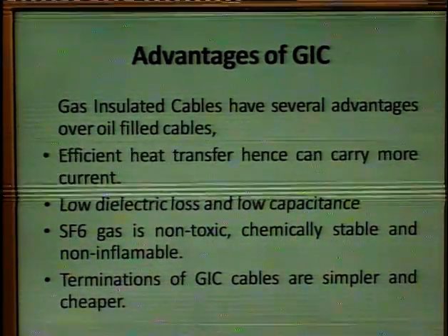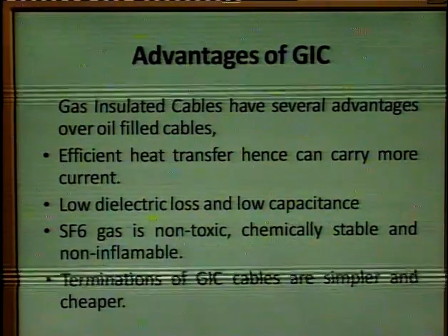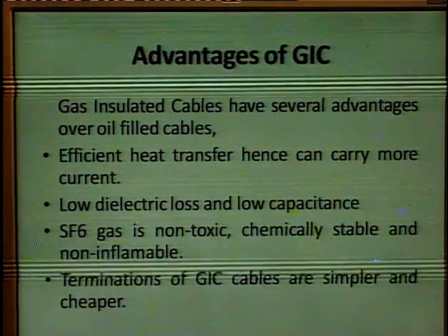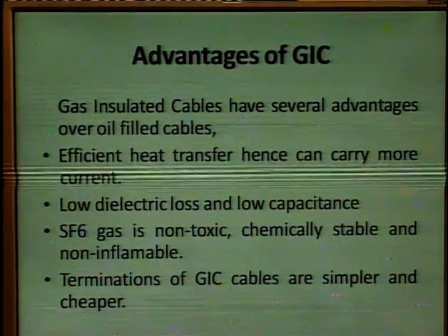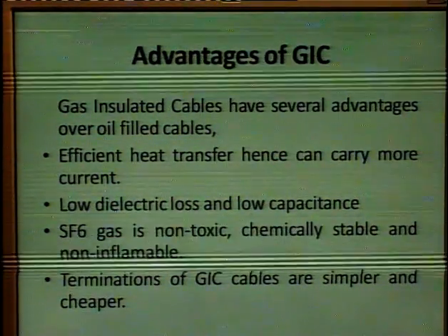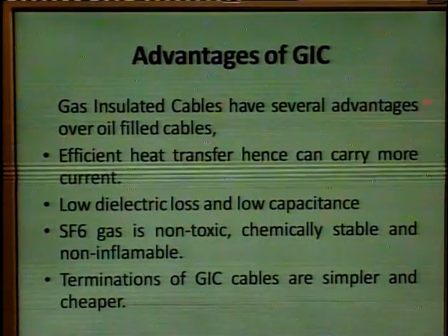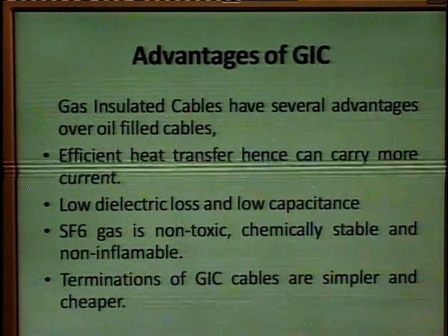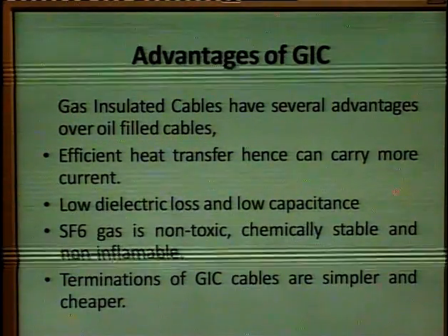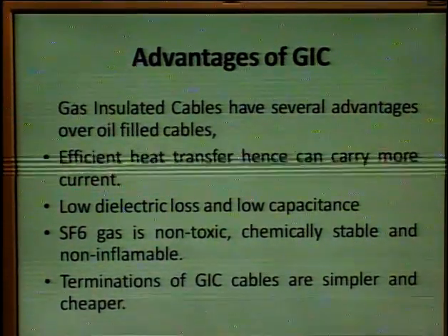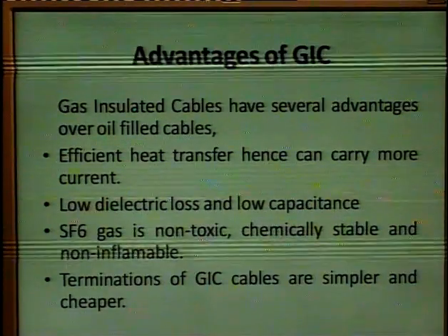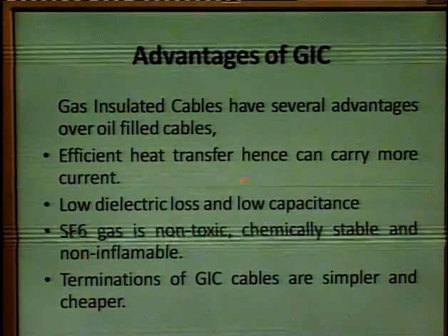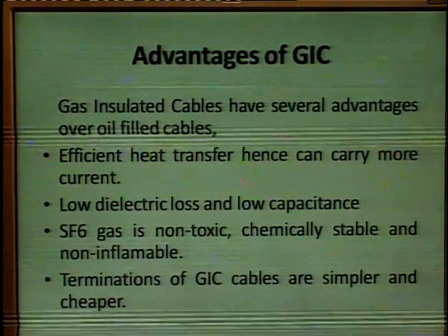Then we have the advantages of GIC, gas insulated cables. The gas insulated cables have several advantages over the oil filled cables. First is the efficient heat transfer properties. So you can say that it can carry more current because the heat transfer efficiency is higher in the GIC.